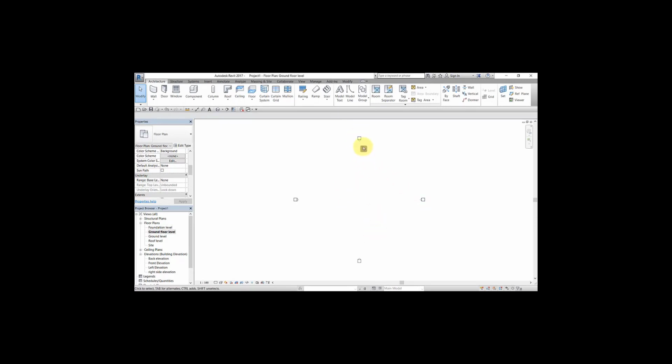Now, these four things you're seeing here are elevation cameras, each depicting the side that it will pick. So this will pick the back of the building, the right, the front, and then this one takes the back. In situations where your structure is bigger than this space, you can pull the elevation cameras to the back and then draw within it.